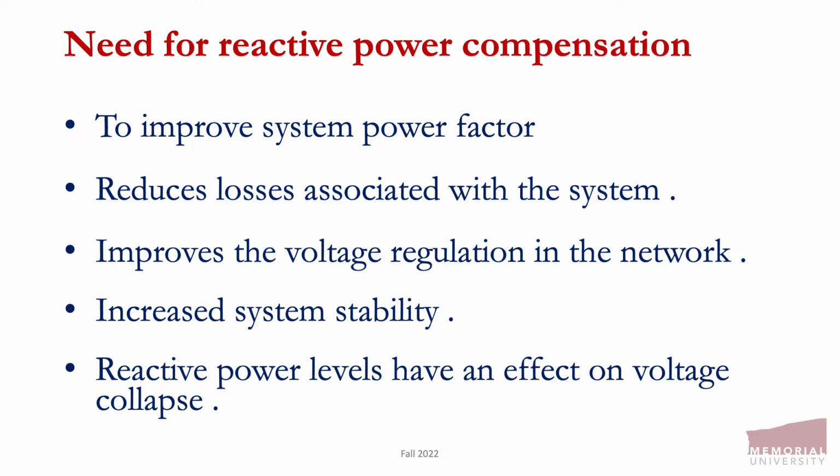Reactive power compensation is defined as the management of reactive power to improve the performance of AC systems. The need for reactive power compensation is, for one, load compensation, and also voltage support. For load compensation, the main objectives are to increase the power factor of the system, to balance the real power drawn from the system, to compensate voltage regulation, and of course to eliminate current harmonics. For voltage support, the main purpose is to decrease the voltage fluctuation at every given interval of the transmission line. Therefore, reactive power compensation improves the stability of the AC system by increasing the maximum active power that can be transmitted.